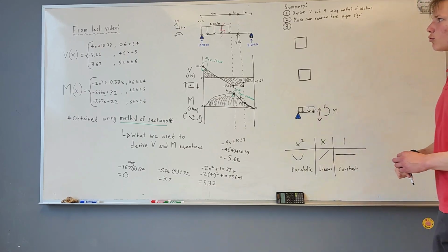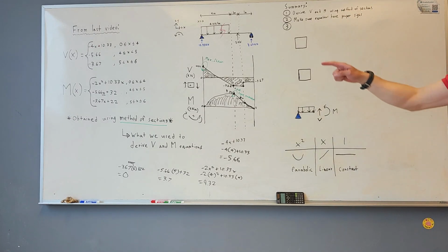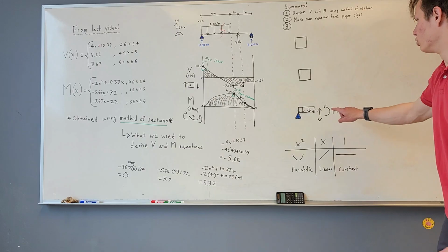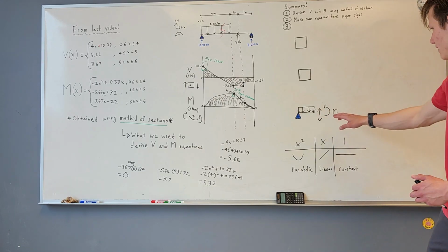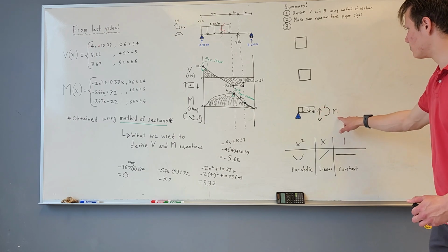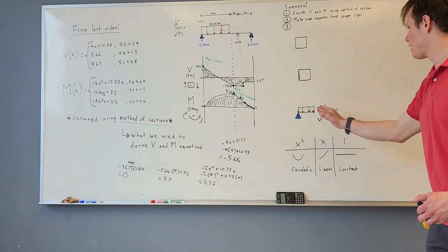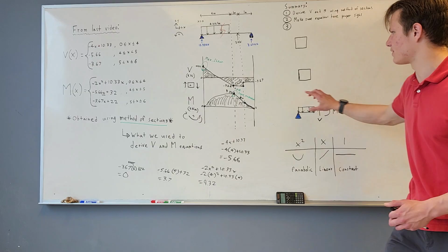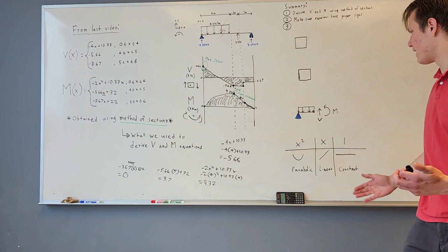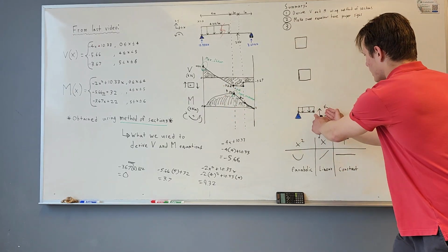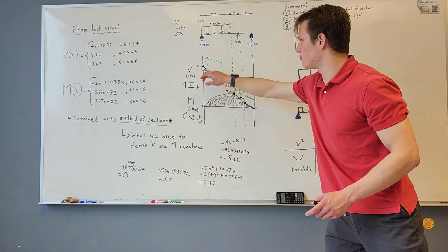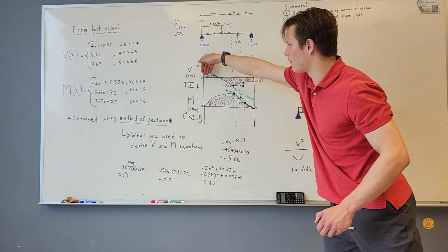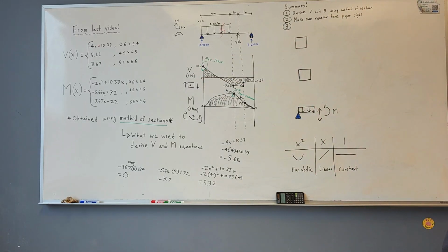And so, remember, the way you check to make sure your equations have proper signs is look at the sign convention, look at the directions you used for shear and moment when you made your cut, and then see, do those agree with the sign convention I'm using here? In our case, our shear on the right was in the opposite direction as where it should be. On the right, we know that positive shear would have a force downward on that side. And then our moment agreed, so we didn't have to change that.